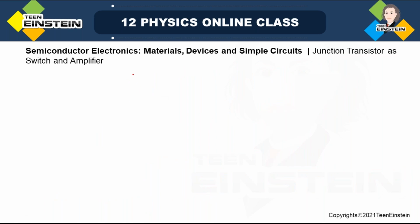Look what I have got: delta VI is equal to delta IB into small r. Small r is actually the combination of the input resistance of the junction plus RB. This is the one, right?